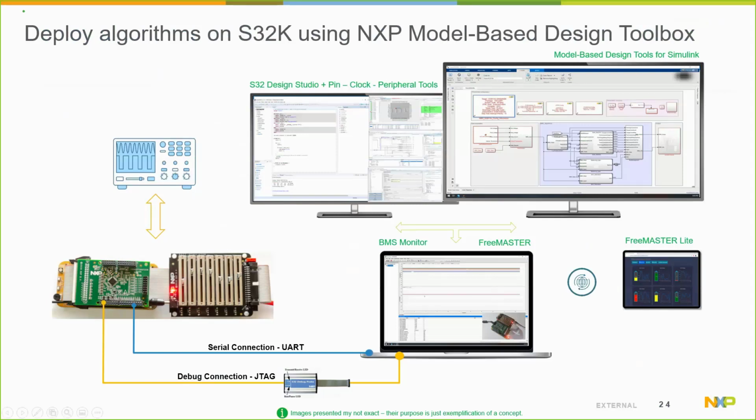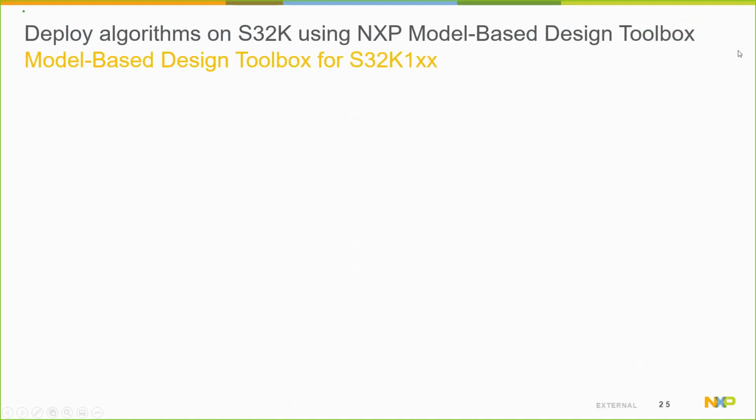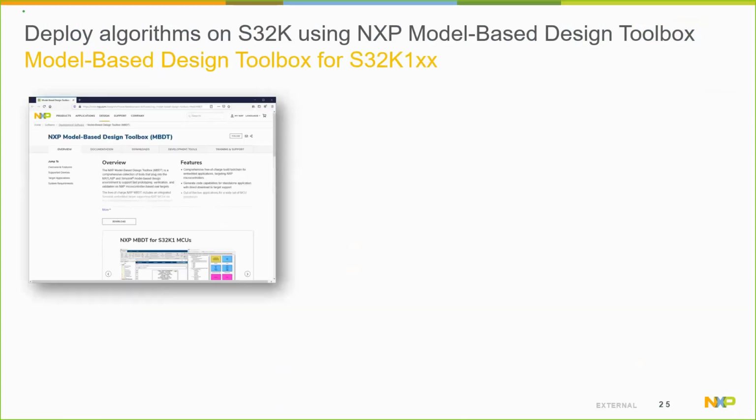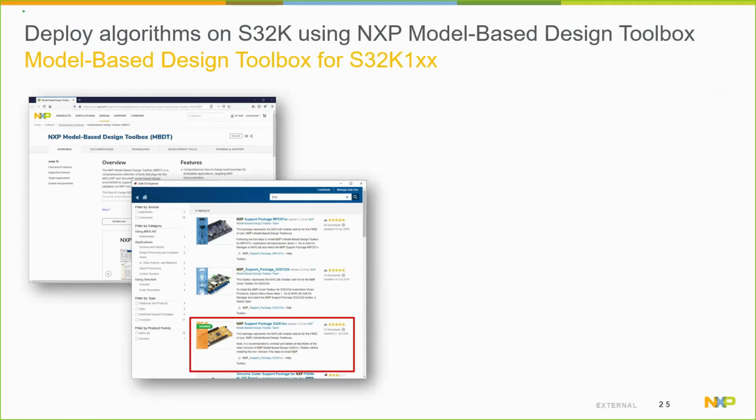All the code that accesses the peripherals is generated on top of the NXP SDKs available for free on the NXP website. If the user needs to debug the generated code, the S32 Design Studio can be used. For today's demo, we use the Model-Based Design Toolbox for S32K1. In case you don't have our toolbox installed already, it is available for free on the NXP website and of course in the MATLAB's add-on explorer.